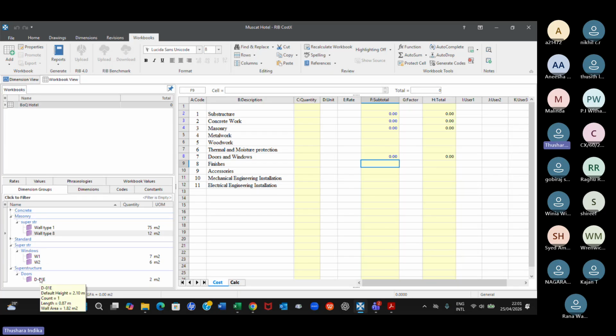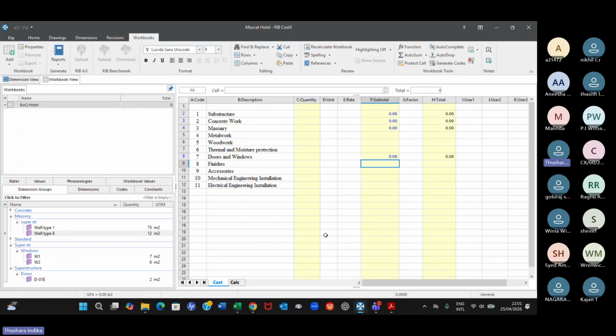If you are measuring floor areas, F1, then you measure the areas. F2, you measure the areas. F3, you measure the areas. And when you measure the wall finishes, W1, let's say, that is where you need to be careful because you need to deduct windows and door openings. Ceilings, of course, again, C1, C2, C3, and so on. You have to measure the areas and include.